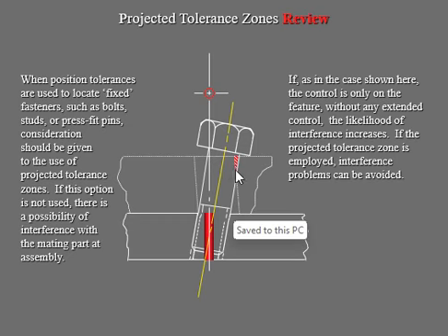Why do we need the projected tolerance? It is to give the extended control, because this little control can't do it. Look at how far away it is from our tolerance zone right here. It's like this much of height that is far away. It's got to be minimum because you've got the head of that bolt. If you take the maximum of it, it's going to even kick this bolt out of it. So the mating surface height got to be up to there, up to this misaligned height, of course.